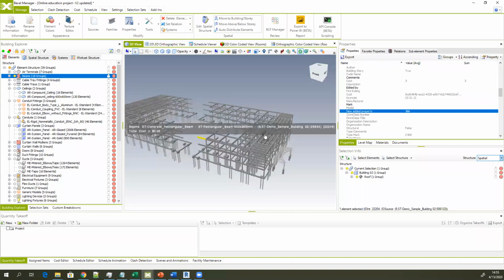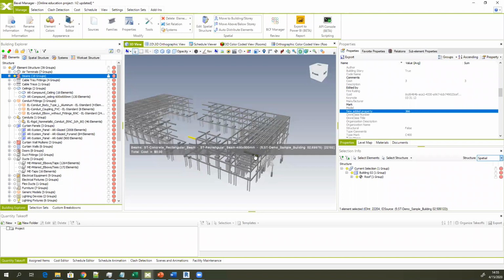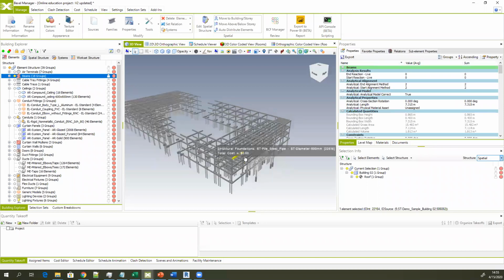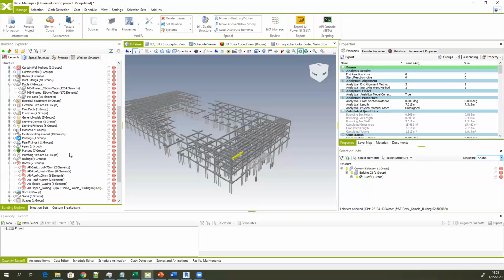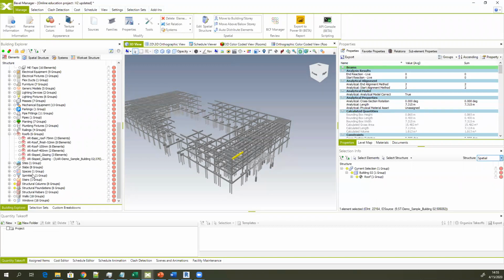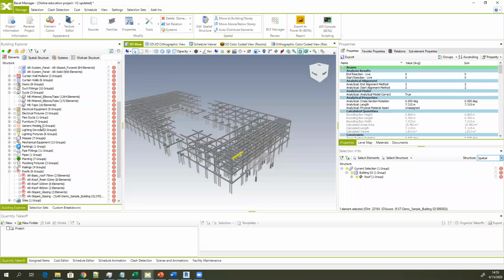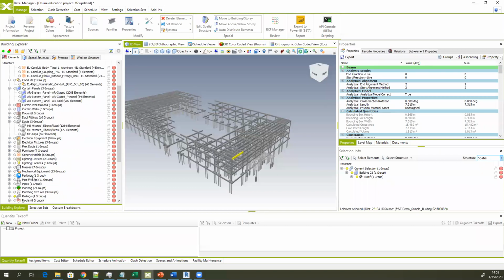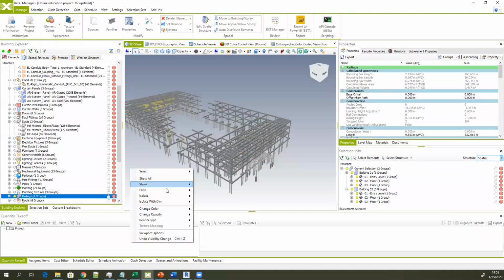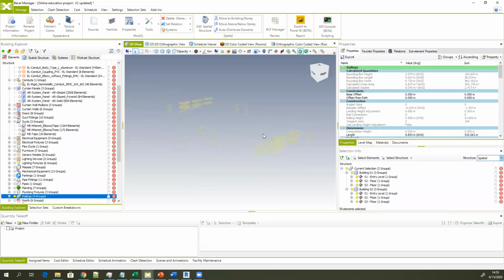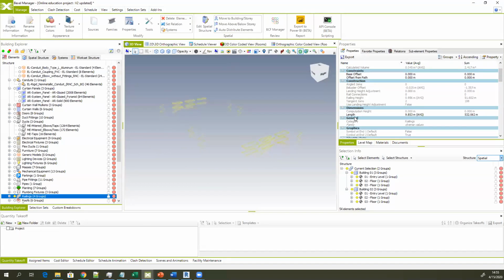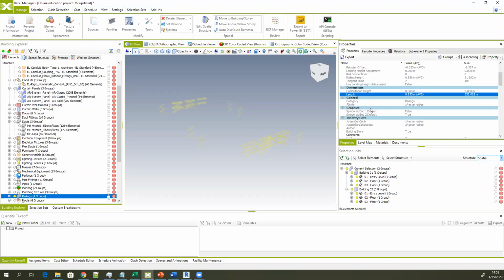Of course, this is not just that. So you can also use the formulas to add some additional property which are not available. So for example, if in this BIM model I select my railings, let me just find the railings, and I can isolate only the railings from the BIM model. You see that the railings, for example, have the length and have the, let's say, computation height, but these elements do not have the property area.